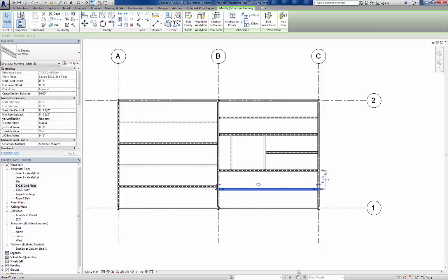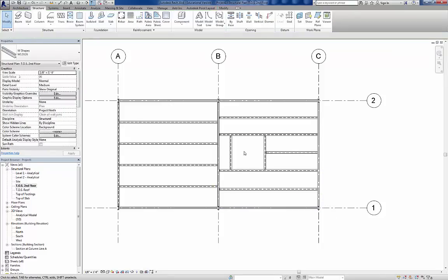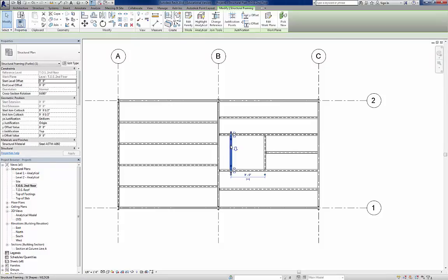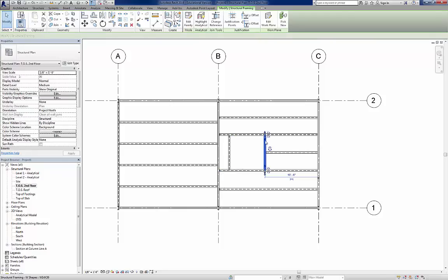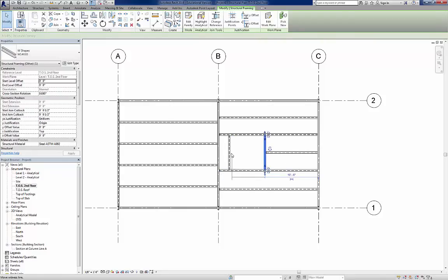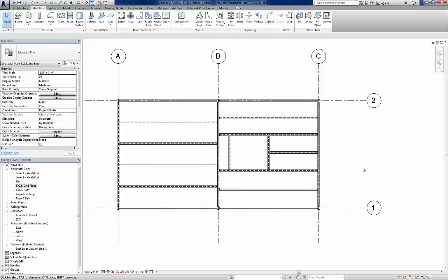If I select that one and I switch the witness line, should be at 5, 3 as well. So we've done that correct. Next, let's check these. So this one right here needs to be, move the witness line back to the center. That should be 3 feet off. And then this one right here, from the other space across this opening in the bay, should be set at 11 feet. Okay, so when you finish step 11, you should look roughly like this.